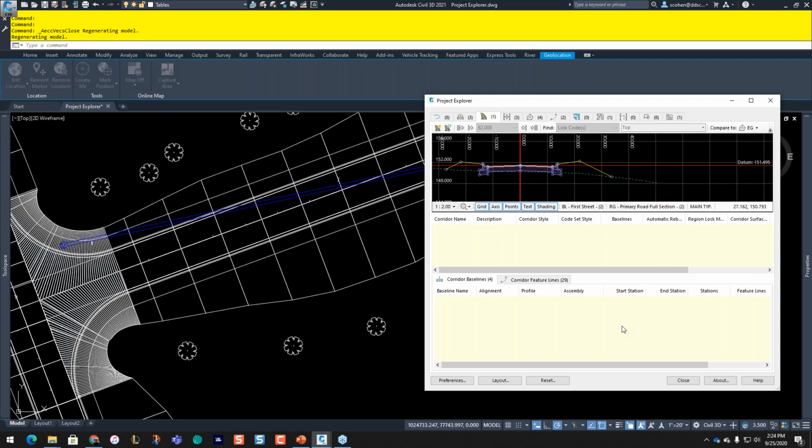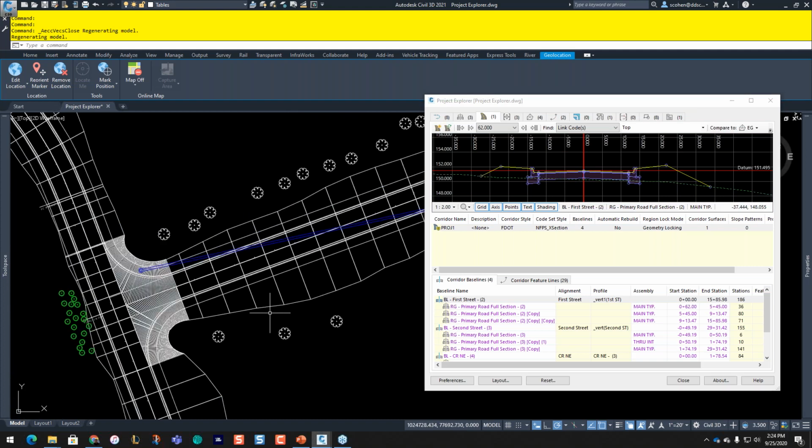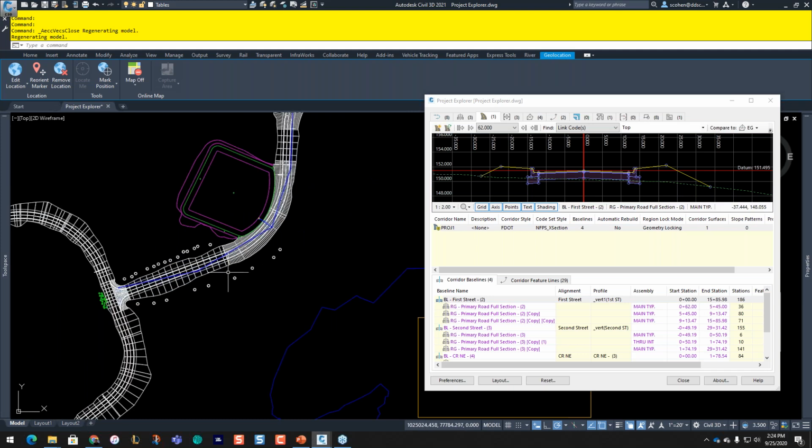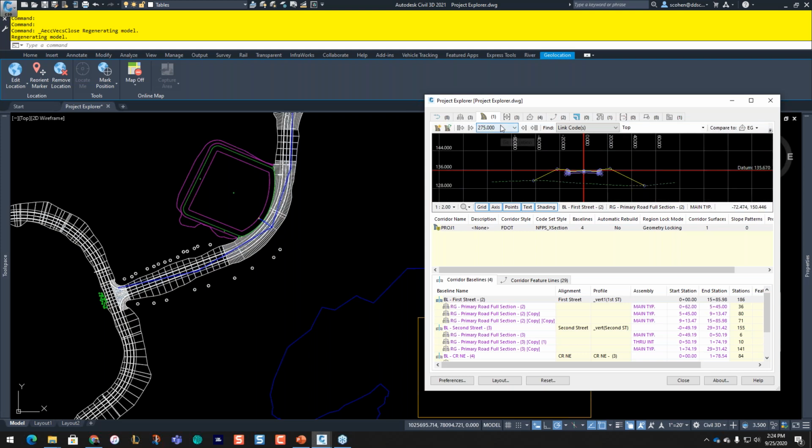All right. Okay, so I've got that shown here. Now, here's a really great thing. To navigate your model very quickly in Section Editor, it's not easy. It just isn't. It takes a while to do. You have to constantly click that next button. Right here, I'm going to click once and keep focus in here. Using the down arrows on the keyboard, you can see how fast this is. This section viewer is fantastic. It is such a nice, easy way, and you can see I'm really going fast. Just seeing my model automatically do that is just fantastic.